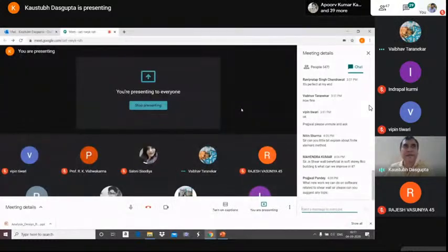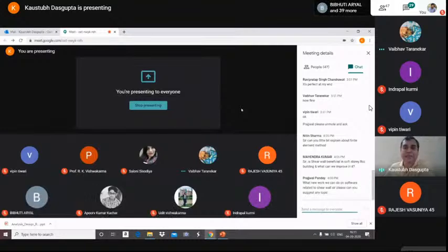See, if it is an elastic model, that means your modulus of elasticity remains constant. So your load deformation curve will be a straight line. If you do cyclic analysis with your elastic model, it will be tracing out only a straight line, back and forth, right? It is elastic. And if you want to see the change in the stiffness, the damage, the degradation in strength and stiffness, that means you have to do nonlinear analysis, right?